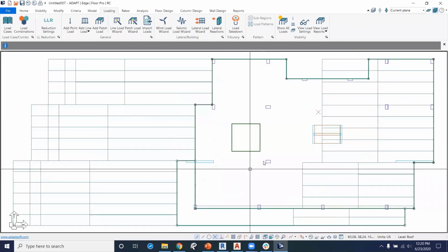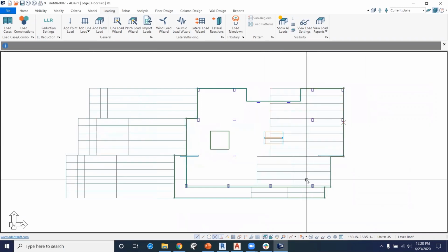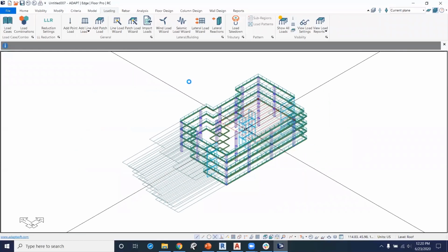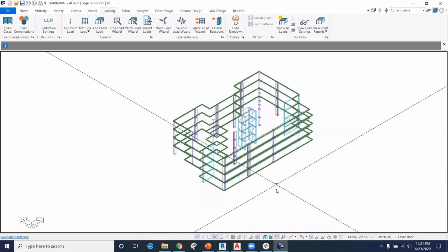In a top-down view, you can actually see we have our windward forces in the X direction and even our leeward forces in the X direction. Now, as you saw, our view is getting a little crowded, so we have our default display button here, and this will just revert the model to a display of your choosing that you saved. I like to just have the geometry shown so I can clear any results or loading, and just keep going back to the geometry as I need to very quickly. So if I click this, you can see all the loads go away.